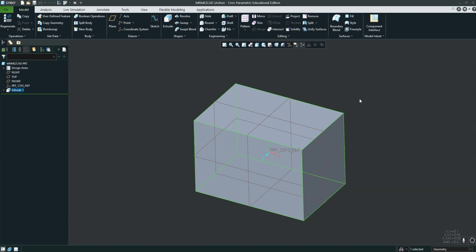All right, so the first thing I'm going to need is to put those rounds that make this thing flip to the sides rather than landing on all 6 sides like a normal 6-sided die would. All right, so we're going to go up to the top. We're going to make sure again we're on the model tab, and we're going to click round.